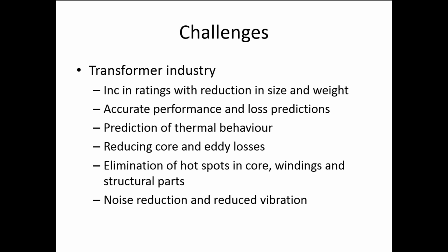Then the next one is, how do I predict the performance and the loss that is there in critical designs and so on. It's important to understand how the performance of your transformers varies across the various designs. And obviously for transformers, the question of thermal management becomes very important. How do you now predict what could be the temperature distribution inside your transformers and so on.